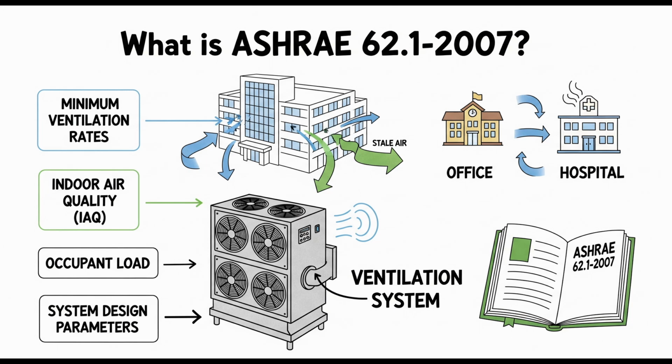Absolutely integrated. Now, once the air is inside, the standard recognizes something important. Not all air within a building is the same quality. Yeah. Section 5.17 introduces air classification. Air has classes, like first class, business class. Sort of, yeah. But based on contaminants and odor. Class 1 air is considered pretty clean, low contaminants, inoffensive odor. Think of a typical office space.